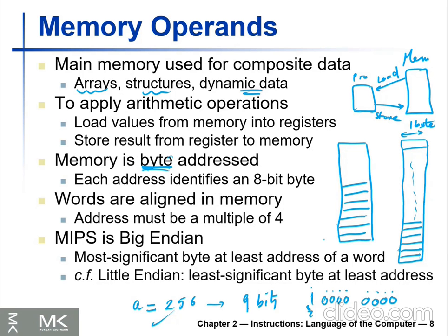If you have 256 locations, you're gonna start from location 0 in hexadecimal to location FF. So you're gonna start by storing here 8 zeros, and then the 1 will be here. And of course, the 1, if you convert it into binary, will be something like this.